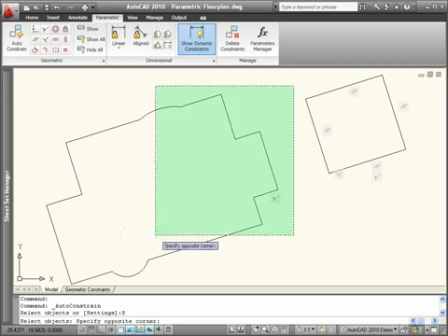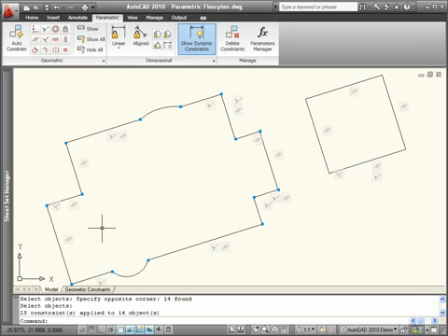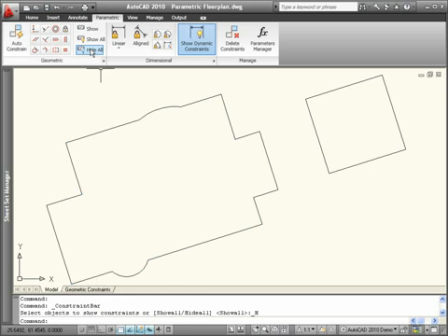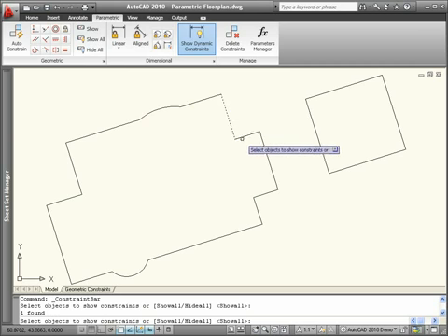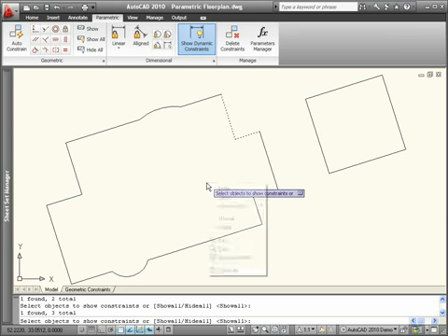Based on the criteria, geometric constraints are automatically applied to the selected geometry, and the constraint bars are displayed. Pass your cursor over the constraint bar icons to view the associated geometry. You can drag constraint bars to change their position, and you can easily hide or show all of them. If you want to display only specific constraint bars, you can hide all of them and then use the Show tool to select the objects for which you want constraint bars to be displayed.